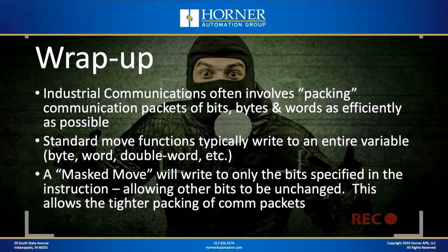Okay, so industrial communications especially often involves packing communication packets with bits, bytes, and words as efficiently as we can, whether you're talking about communications over cellular or satellite, maybe communications that's doing some lighting sequencing, whatever the case may be. Standard move functions and standard bitwise operations typically write to the entire variable instead of just a portion of the variable.